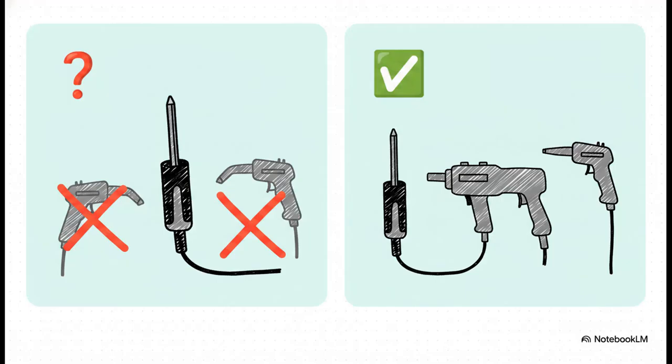Oh, here's another classic mix-up. An engineer might put E70XX on a drawing. Now, they're probably just trying to say they want a filler metal with a standard 70 KSI strength. But that E70XX format is actually specific to one kind of welding, stick welding. So they've accidentally told the contractor they can't use other, possibly faster methods. The right way to do it? Just specify the strength you need and let the contractor pick the right tool for the job.